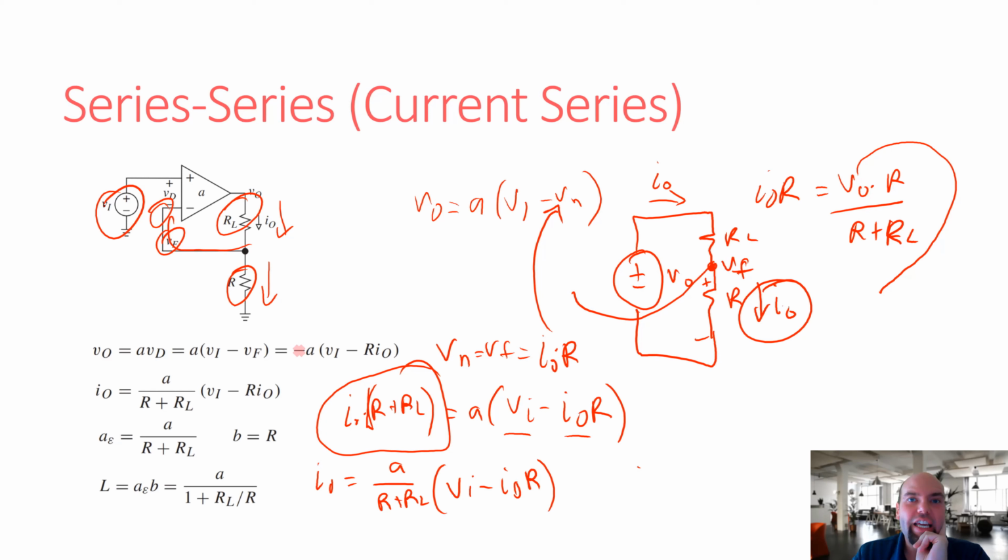There is a test that I use, and again, I don't pull this from any textbook, but the test that I use in my head is if I change the output load resistance, does my voltage change? So if I wiggle my output load resistance, does my voltage change? In this case, it would.